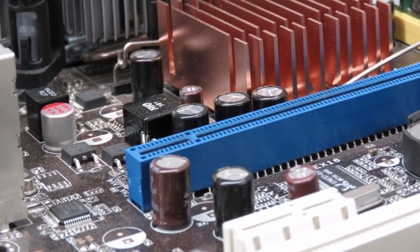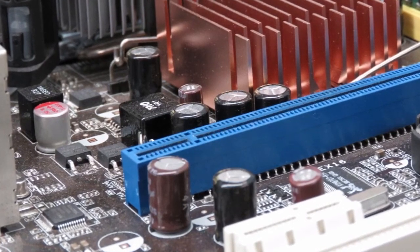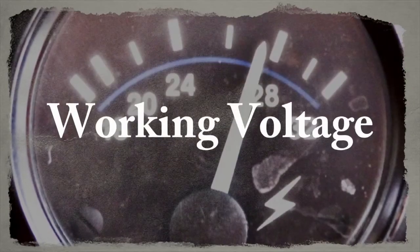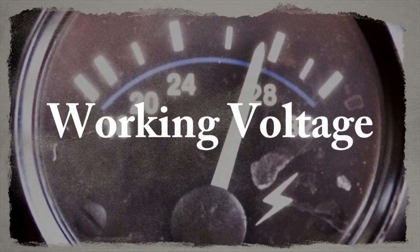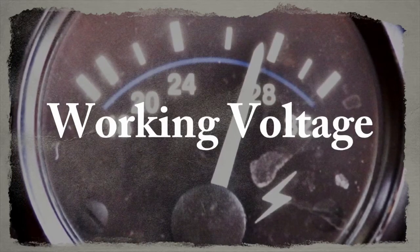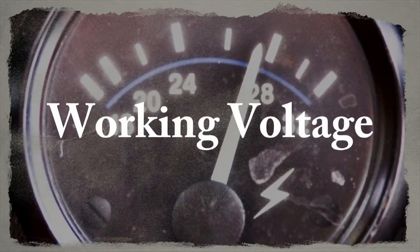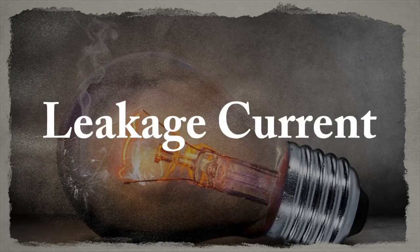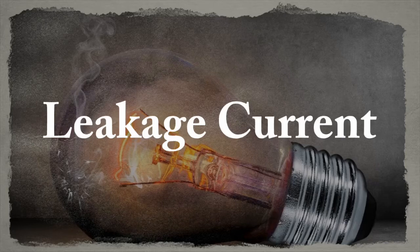When choosing a capacitor, besides the value, the tolerance and the stability, there are two additional factors which should be considered. The first one is the working voltage. This is the largest voltage which can be applied across the capacitor and is often marked on it. If it's exceeded, the dielectric breaks down. The second one is the leakage current. No dielectric is a perfect insulator, but the loss of charge through it as leakage current should be small.